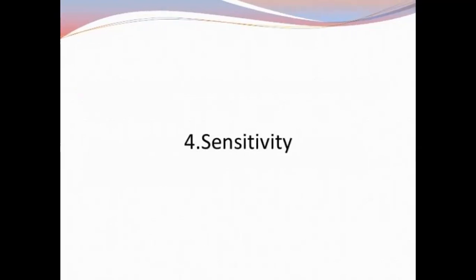How about microphone sensitivity? Sensitivity basically refers to a test's ability to designate an individual with disease as positive. A highly sensitive test means that there are few false negative results. Microphone sensitivity is the amount of output for a given input. The input is the sound pressure level at the microphone diaphragm. When measuring microphone sensitivity, a standard 1 kilohertz tone is used with a sound pressure level of 94 dB SPL or 1 Pascal.